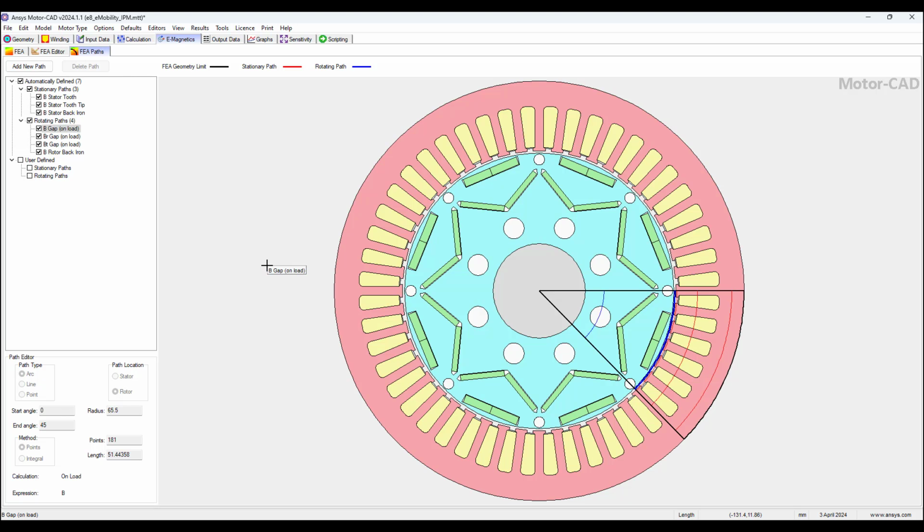In this case, it's a 1/8 symmetry model, as shown here with this pizza-shaped slice. Instead of 1/8 symmetry, if you want to see more than just a 1/8 slice, you can model the full model, or you can model a half symmetry, right, depending on what you want.